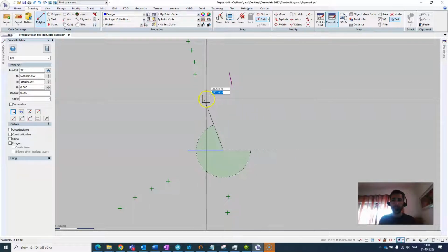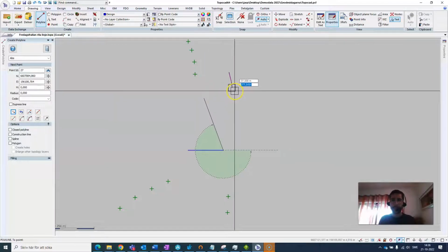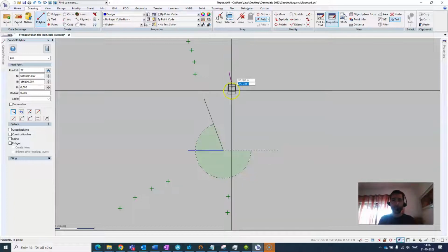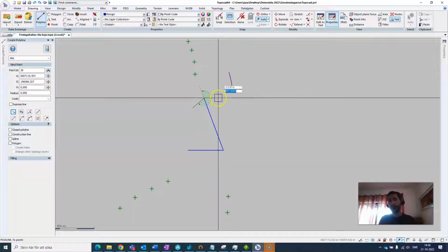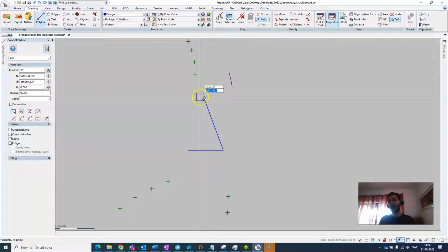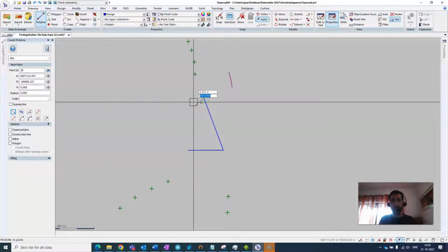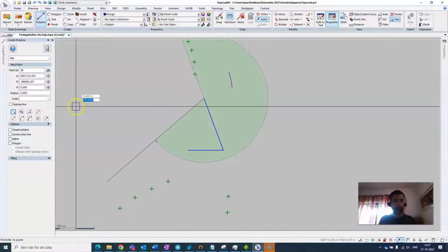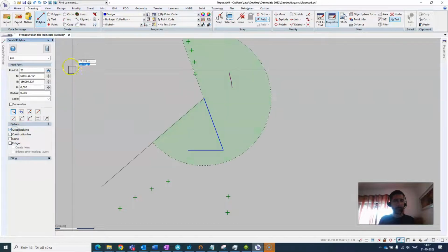And now I can, for example, snap to something to the side of this direction, and I'm still drawing in the locked angle. And this is something that can be quite useful, and it's something that was a little bit more tricky to do a couple versions ago. And here I can just close this polyline.